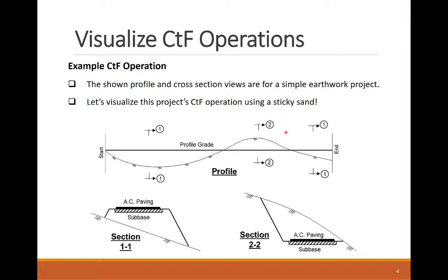That's fine and actually typical in earthwork projects because the purpose of these sections is not to provide the cross geometry dimensions. Otherwise, you will need to provide a section view for every meter or foot as the geometry changes over the length of the project. The cross-section view usually is given with variable dimension, with the main purpose to show the general geometry of the section, its slope, and layers.